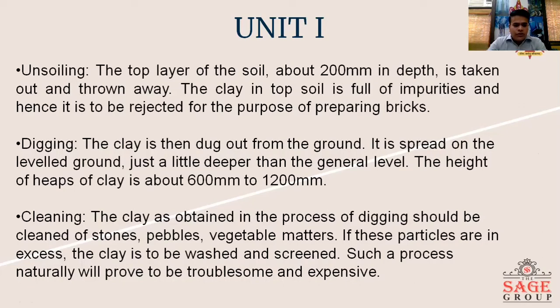Then the digging process. The clay is dug out from the ground, separated, and spread on level ground, just a little deeper than the general level, with the height of the heap of clay about 600 mm to 1200 mm. That means the clay which is dug out is spread on the level ground so that the impurities and the moisture present in the extracted soil can vanish off.